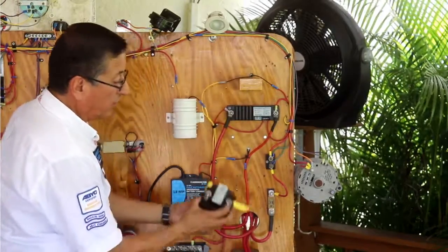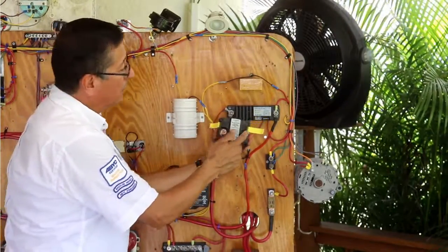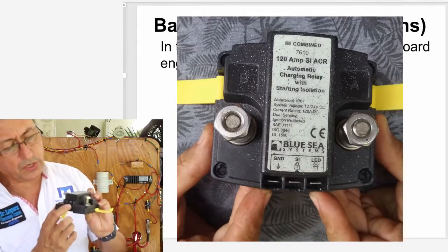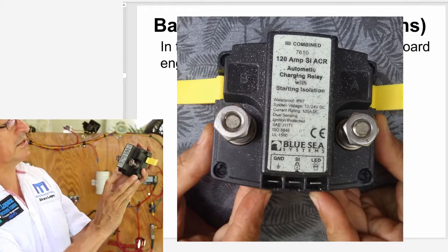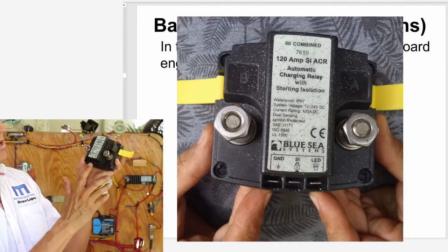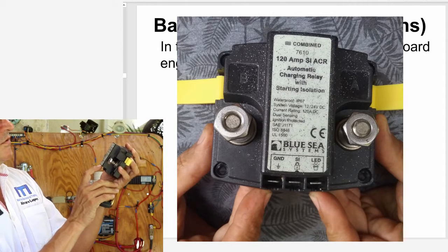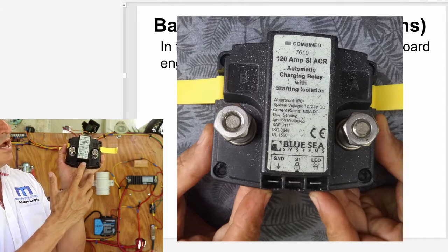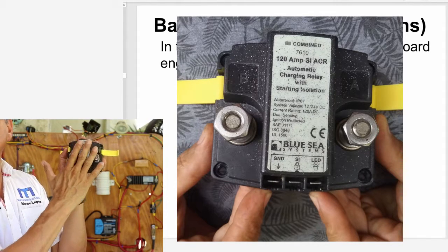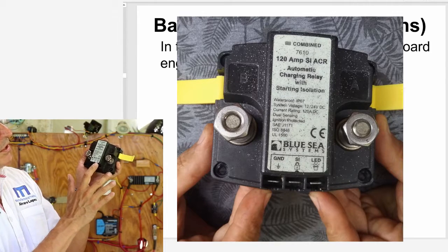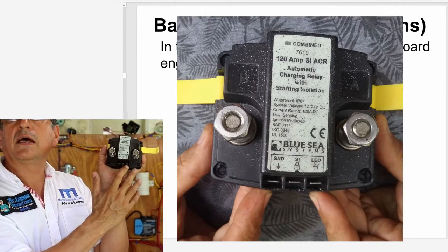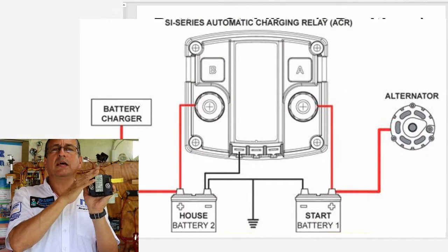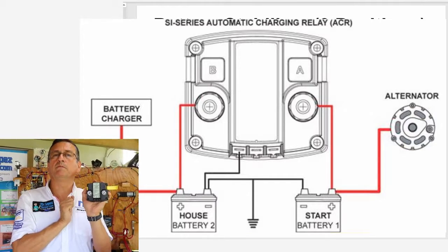You can use this one or this one. This is exactly the same. Those ACRs have three terminals on the bottom. The first terminal should be connected to the ground. The second terminal is to start or stop the ACR, connect or disconnect. And terminal number 3 is an LED, and that LED could be connected on the dashboard to indicate that the ACR is running, is working.